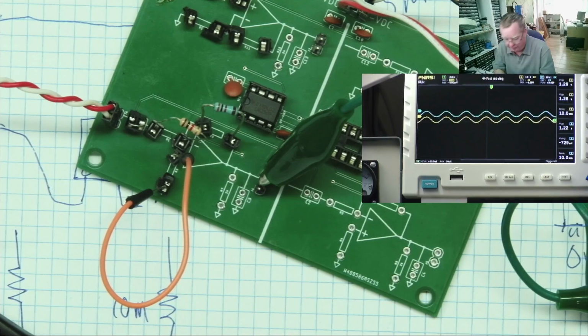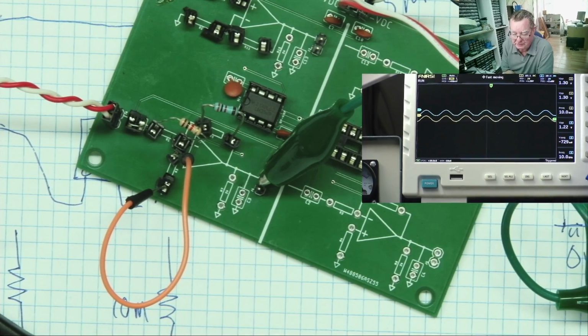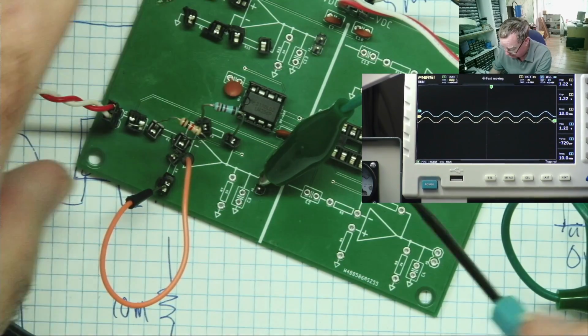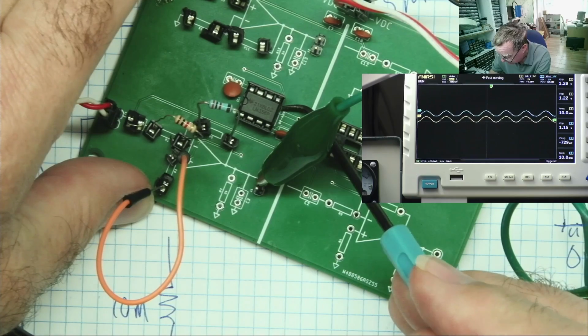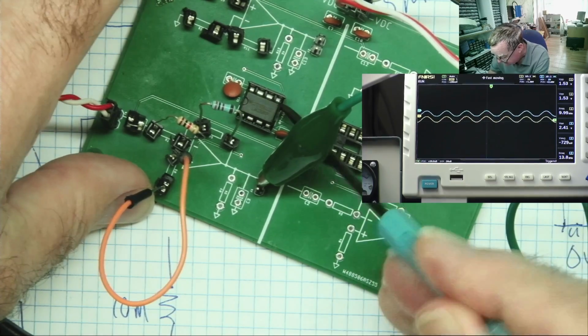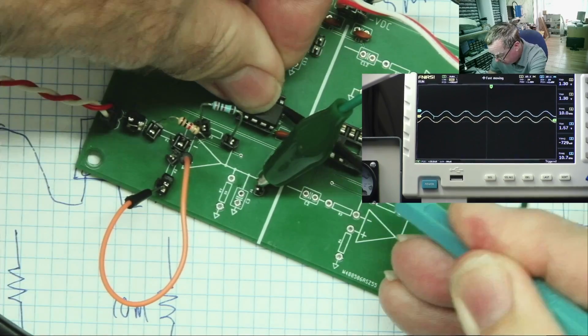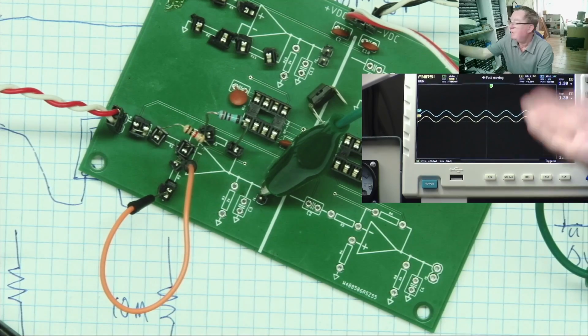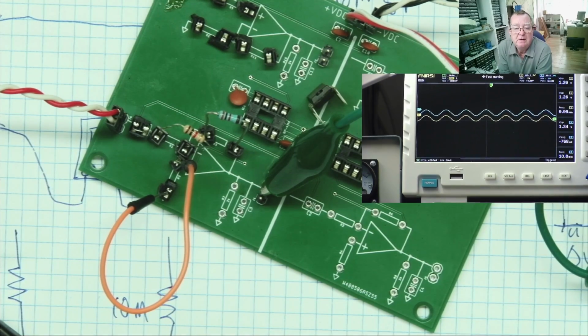Well, the output that we see from the op-amp is not coming through the op-amp because the op-amp has no power. And I can prove this quite readily by just removing the op-amp chip. Okay, so we get the op-amp chip, and we'll take it out of the board. Okay, it's gone. And we still have the same output. So the output is the same now whether the op-amp is there or not. Let's draw this and that'll become quite obvious if it wasn't already.